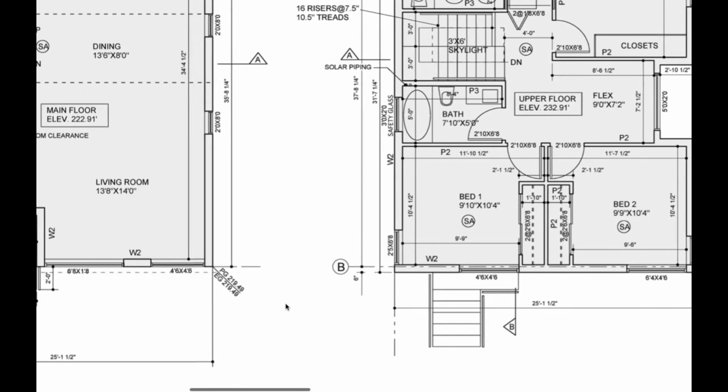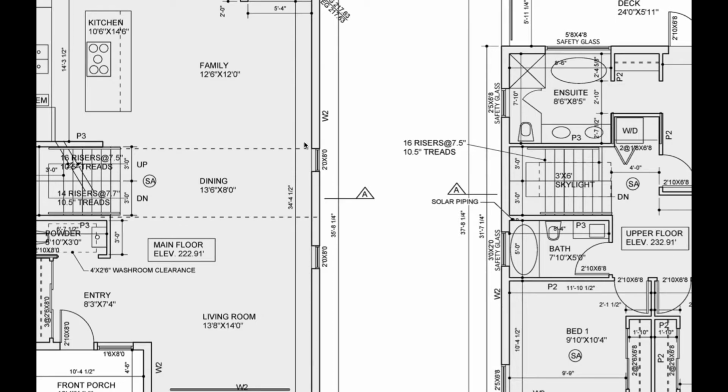So these stairs are still on the main level here, so that's not actually part of this. It's just showing that they still exist. It looks like on this side over here, that's a straight shot on the wall down below, but up top it actually scooches in a little bit. My guess is that the square footage requirement was exceeded if they had a straight run, so we have to jog back and reduce some of this square footage so they can maintain code compliance. So up top, you come up the stairs. It says that there's a skylight above, so we'll probably see that on the roof plan.